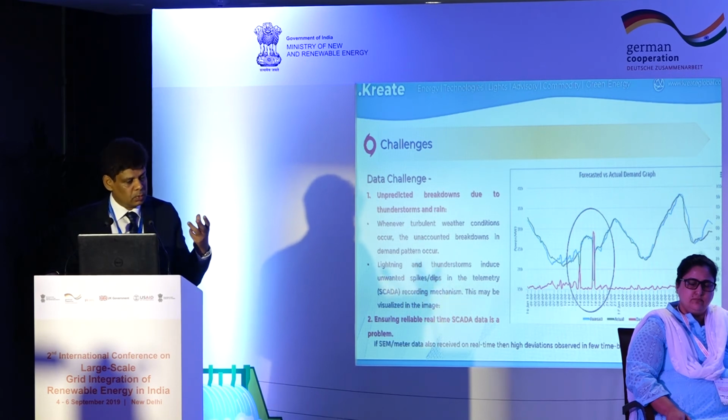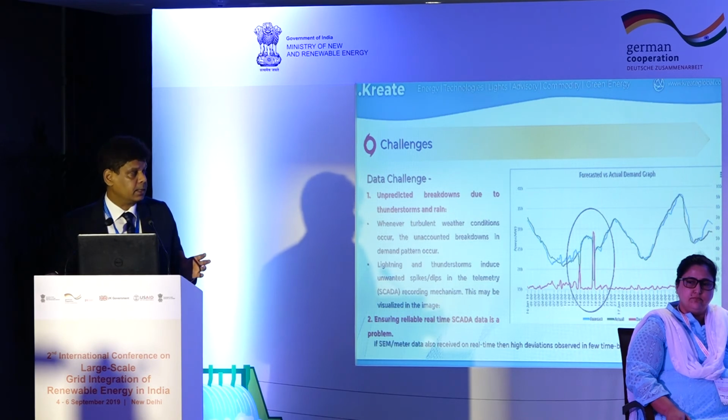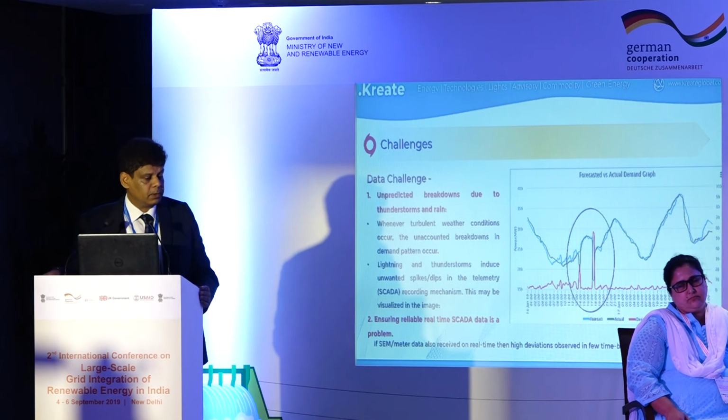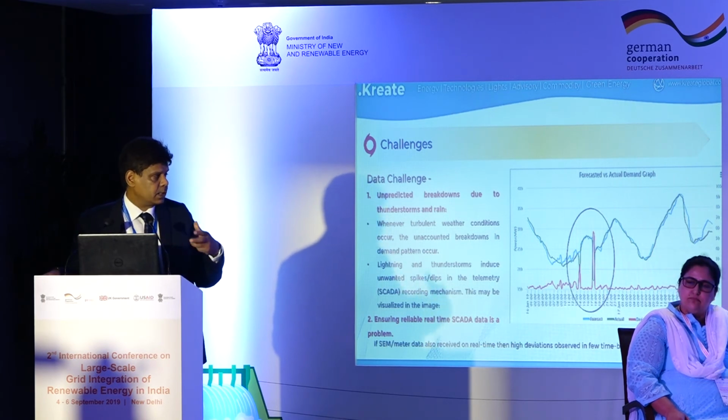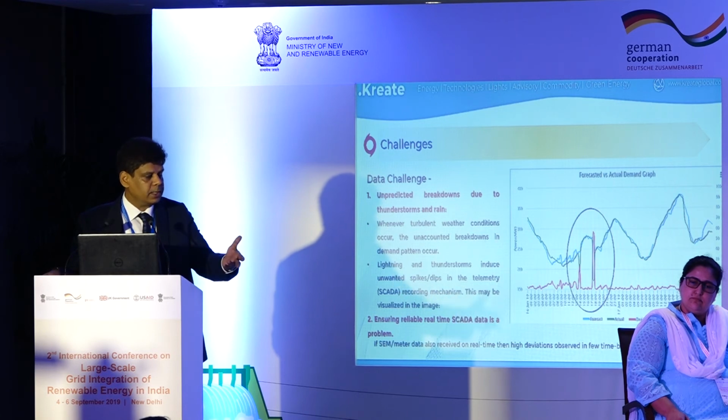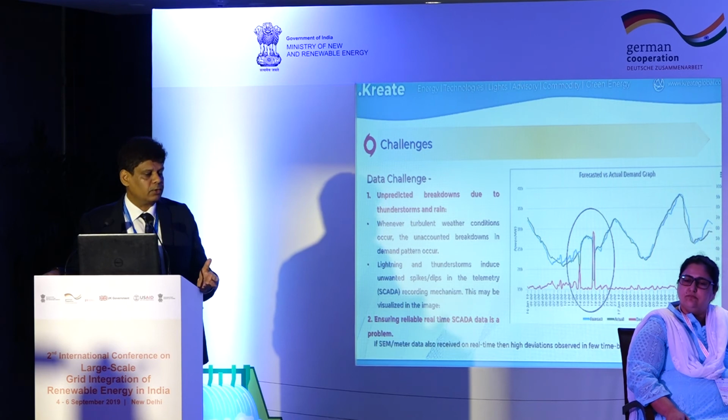So here the solution could have been that the SCADA telemetry data is improved, plus SCADA data is backed by the meter data on a real-time basis. If the meter data is also coming on a real-time basis, there would have been a way to correct that error, because the meter is what you're doing the billing on, but meter data is not coming in real time.